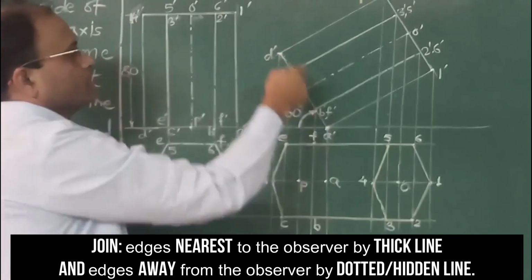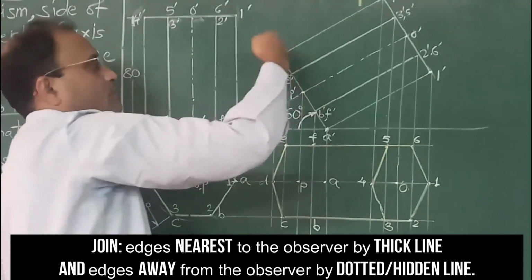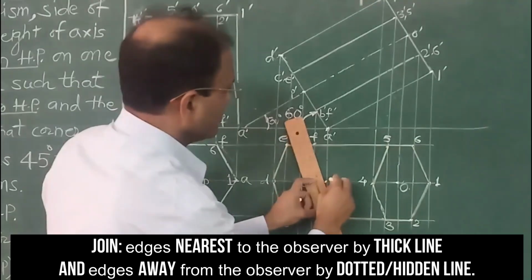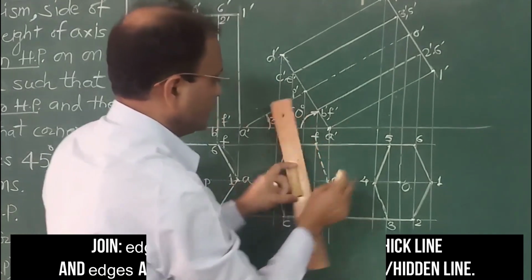Then the points of the base, that is the alphabets, they are not visible. When you look from top, this part of the prism is not visible. That's why we need to connect the remaining edges by hidden lines or dotted lines.